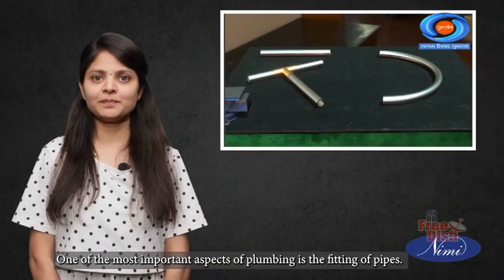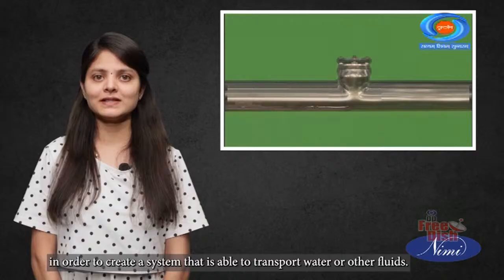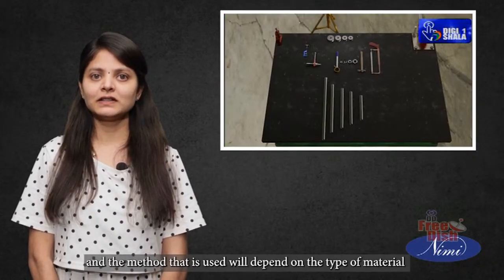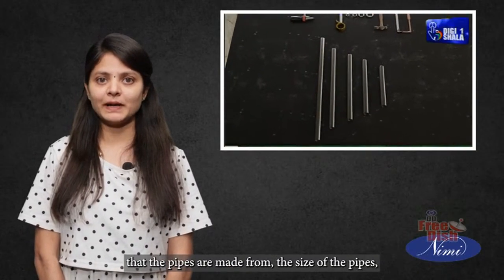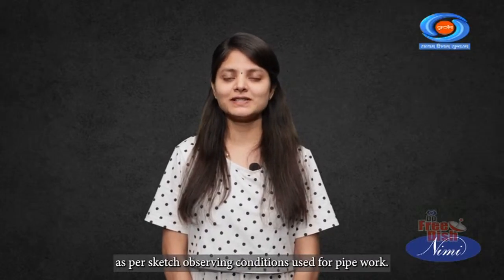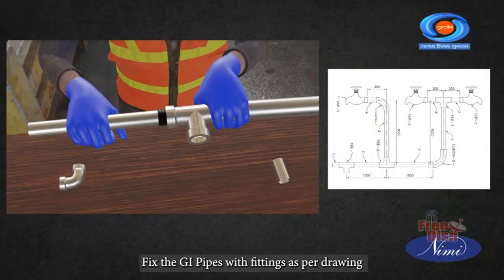One of the most important aspects of plumbing is the fitting of pipes. This is a process that involves connecting 2 or more pipes together in order to create a system that is able to transport water or other fluids. There are a number of different ways to fit pipes together, and the method that is used will depend on the type of material that the pipes are made from, the size of the pipes, and the type of connection that is required. Today, we are going to learn about fitting of pipes as per sketch, observing conditions used for pipe work. At the end of this demonstration, you will be able to fix the GI pipes with fittings as per drawing.